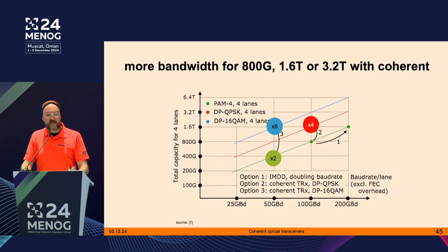And now, just add a DSP inside which is doing a modulation to DP, dual polarization, 16 quadrature amplitude modulation, you end up at 1.6 terabit, just due to the fact that there is a chip in there which does a little bit of mathematics. So you quadruple the capacity of your link tremendously. That's pretty amazing.